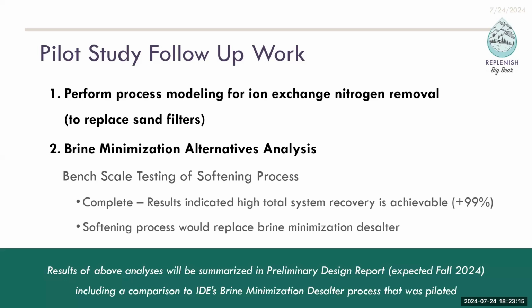Yeah, the lime basically helps remove additional dissolved constituents that would scale up a downstream RO membrane. We actually do have a slide showing the process. I can skip to this last slide if that will help. But basically, the whole game with reverse osmosis is how much can you push through it without scaling or fouling the membrane, because that's what limits its ability to produce water at the target recovery you're trying to achieve.